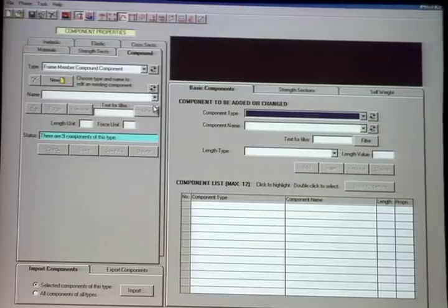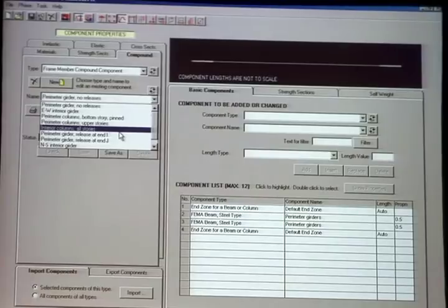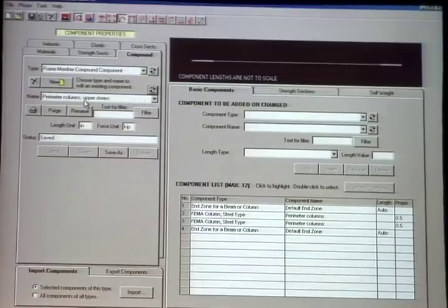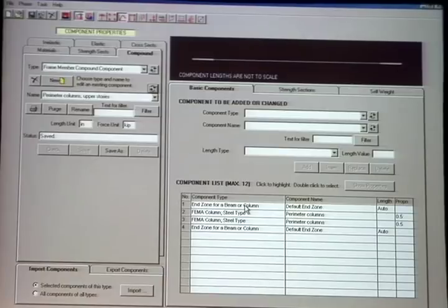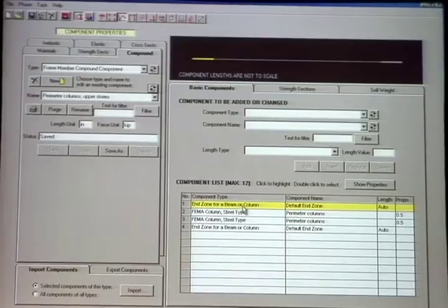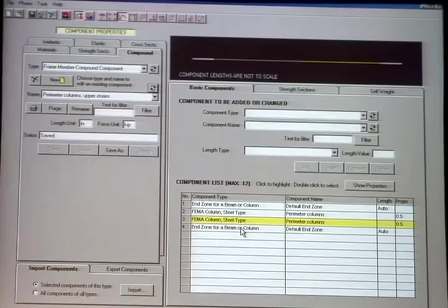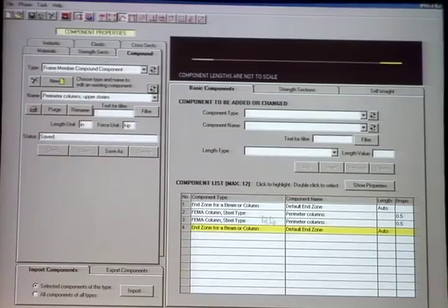And what I'm going to do next is to go into the next thing, which is a column. Yeah, let's do the next one. This is going to be a FEMA column, and it consists of four things. It's got an end zone. I hope you can see that in yellow. It's then got one of those things I just defined, and what is called a FEMA column component. And I was just looking at it a moment ago. That's for the first half, and for the second half, and then a rigid stiff end zone again. This is a column, so it is actually vertical.